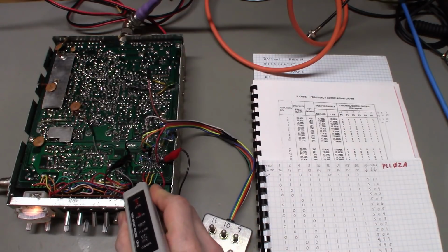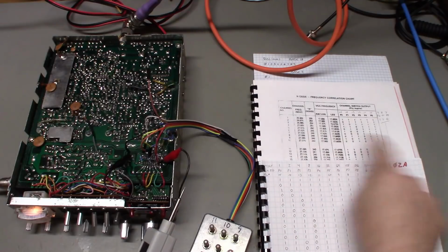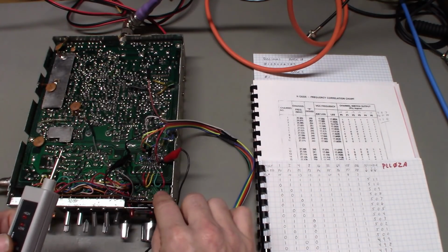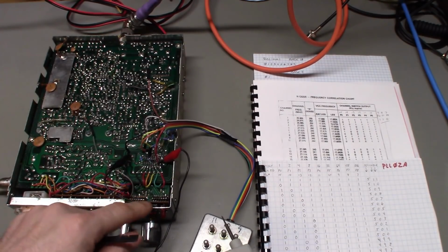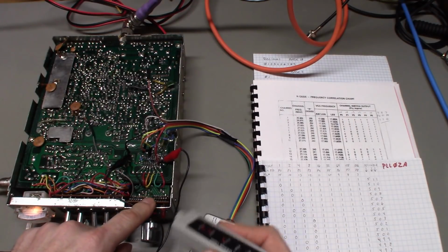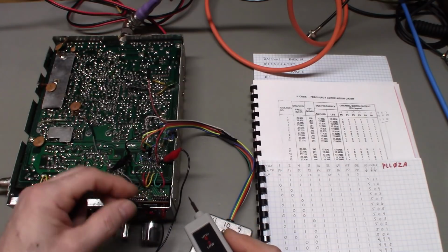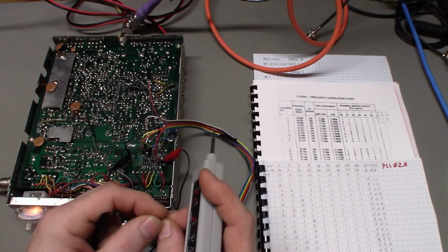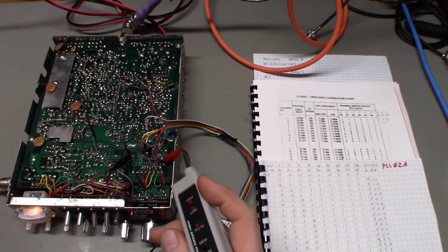Stick the radio on a channel, buzz out each of the pins and see what their state is and write it down. If you're having a problem, you don't know, maybe your channel selector switch is bad. Some channel selectors back in the day, and even actually into fairly recent history, had those little flat flex style cable. It wasn't really a circuit board like this one down here. They had that flat flex cable, which those things are fragile. And they commonly get circuit traces broken on those things if the radio's been apart a couple times.